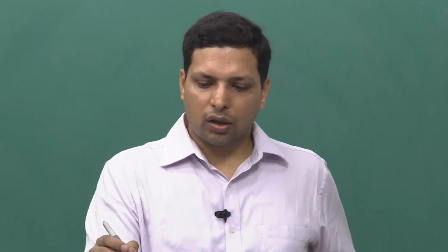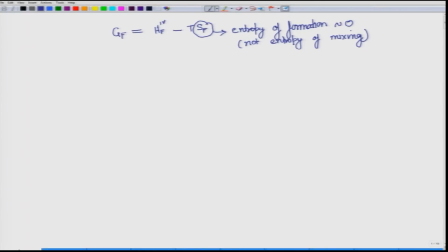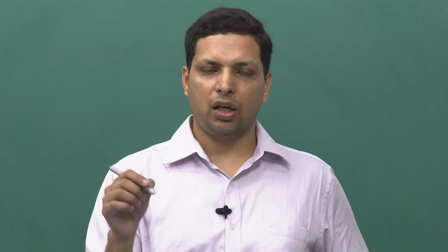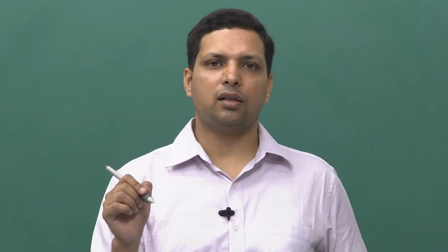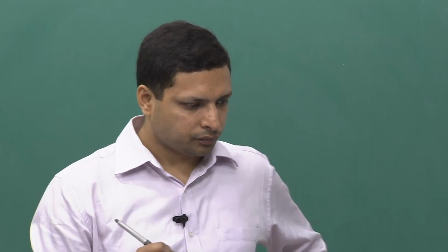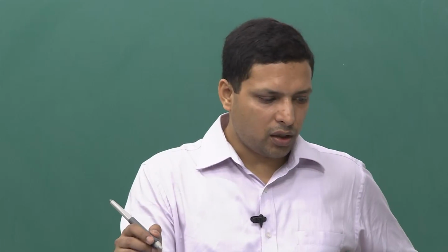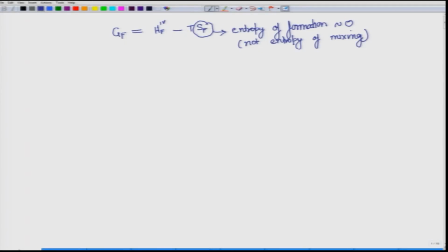So, the total energy reduces, but at the same time the H term keeps increasing. There would be a counterbalance to H by this entropy term, and therefore there will be a minima in the G, which is what we want to find: at what fraction of vacancies in the system that minima occurs.